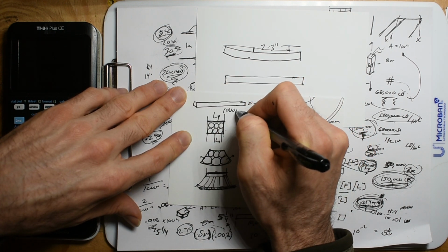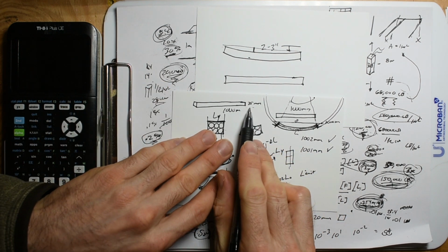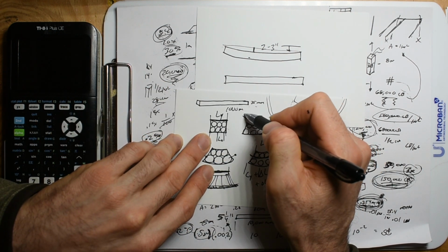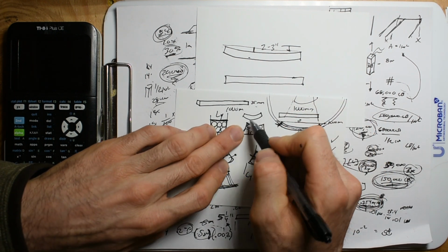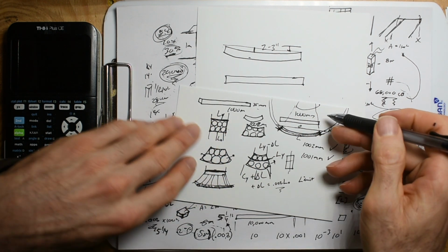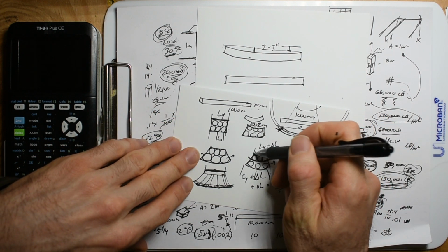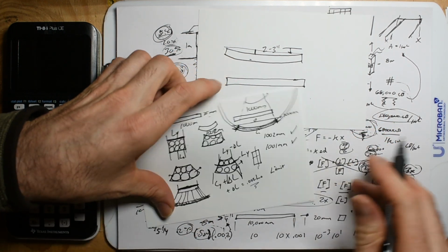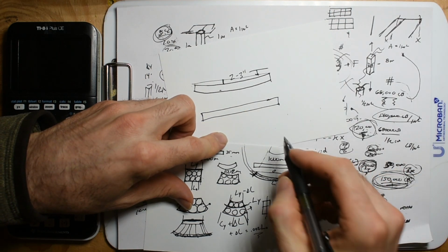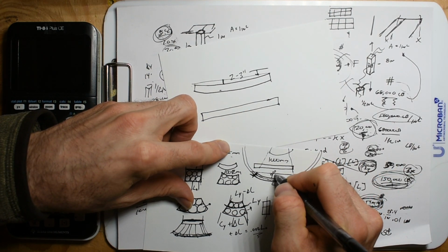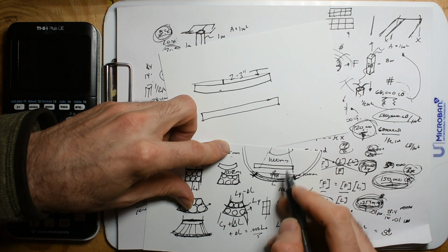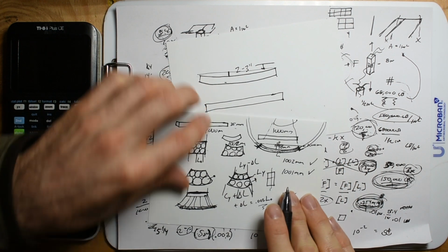So we got 1,000 millimeters, 25 millimeters. Just know that I could bend it into a smiley face, where the bottom goes to 1,002 millimeters. The top can do equal in compression. The change in length is the same based on those principles that we talked about right here. And the top can get reduced by 2 millimeters, so it's going to be 998 millimeters.